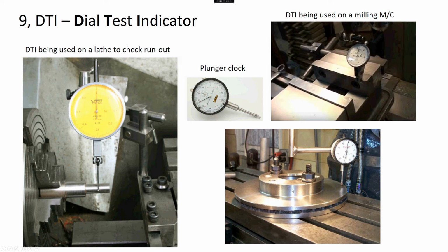So if you had datum C here, if you had to machine some holes in this relative to this hole here, for example, on this particular machine you can't actually spin the axis. So what you'd do is you'd put a round block at this location and a round block at this location through this T slot, and you'd push the block up against the part here and here. You make sure this is flat first and you'd probably shimmy it out, but then what you do is you undo these two bolts a fraction, you'd move the machine across to the right location of this hole, and then you'd physically rotate this part until this hole was at top dead center, for example. And that's how you'd set up datum C.